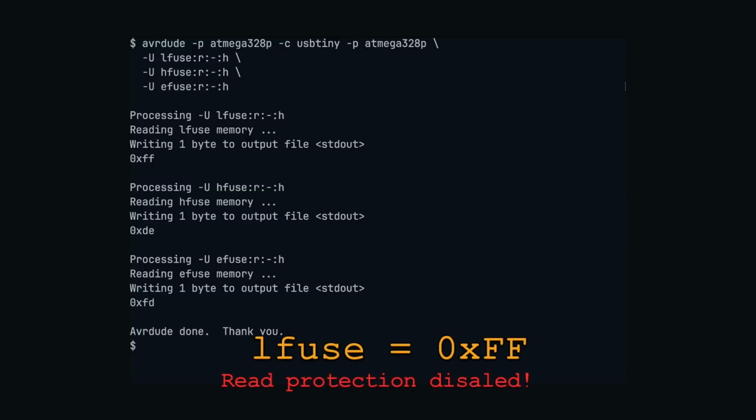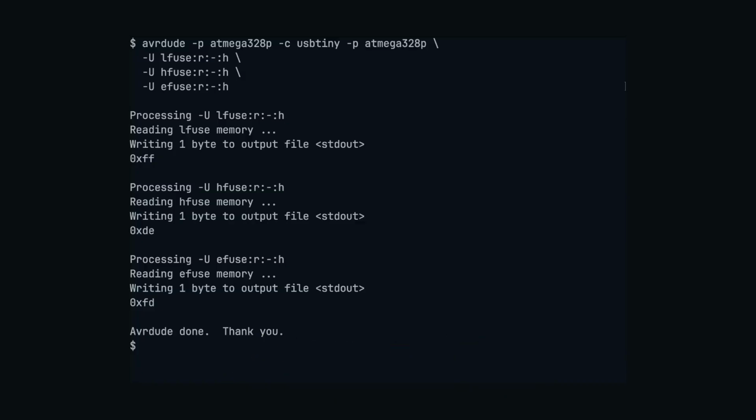Of course, this is further evident by our attack. Since this pin is set to high, we can determine that read protection is not enabled. To defend our system, we can set this pin to low to prevent firmware readout. This will prevent an attacker from exposing the firmware.